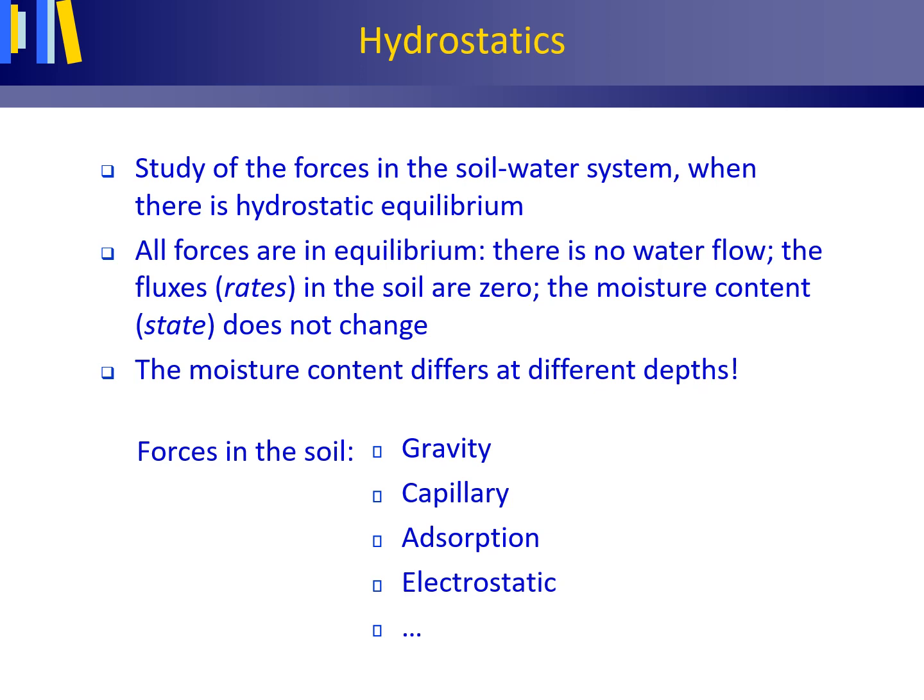However, as mentioned before, we as hydrologists need not worry too much about the exact forces with which water is bound to the soil matrix in the unsaturated zone, as we have a unifying concept for this, which is the concept of negative pore water pressures in the unsaturated zone. For this, we need to take the existing air pressure at the water table as a reference or zero level. Let's take a better look at this concept.